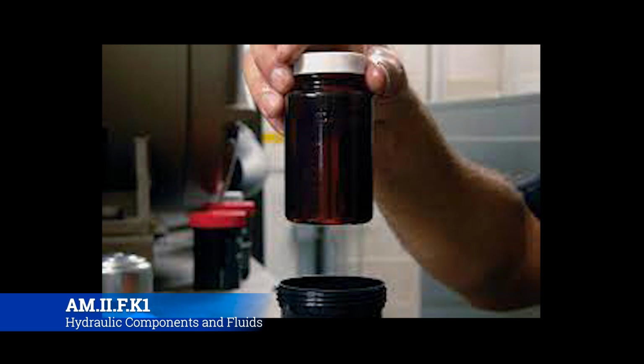If you get into helicopters, transmission drain and service is something that happens on a regular basis. If you get a positive hit on a chip detector, a drain and service is one of the first things you're going to do, to try to get all the metal out before you end up replacing any big components. And so that's a task that you can pretty well bet that you're doing.